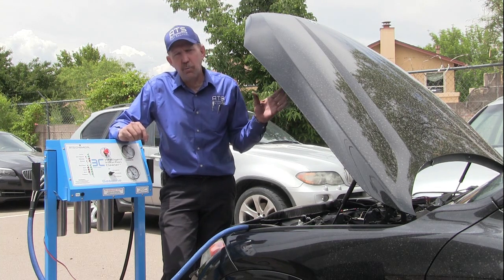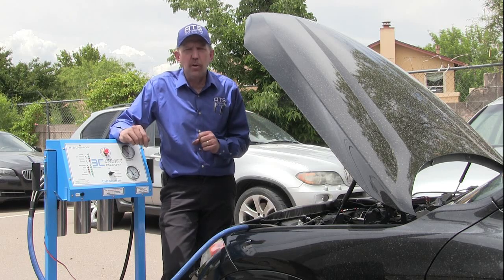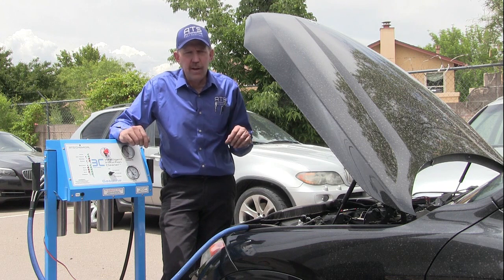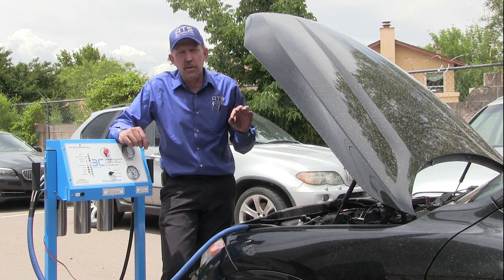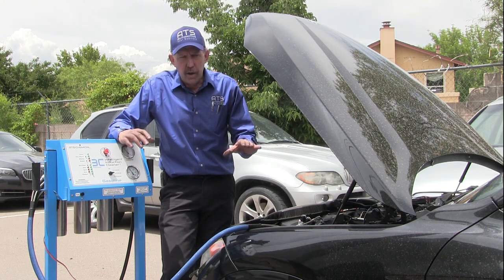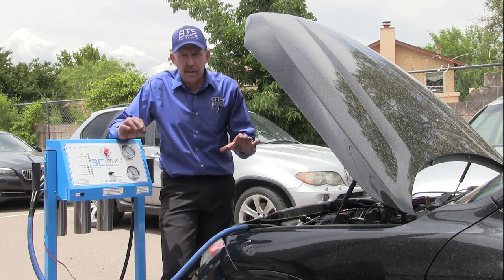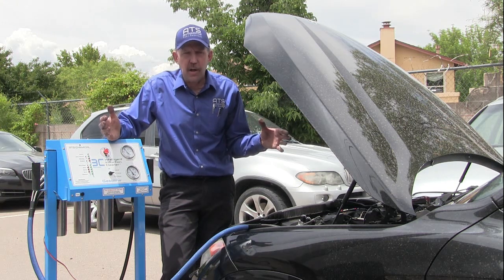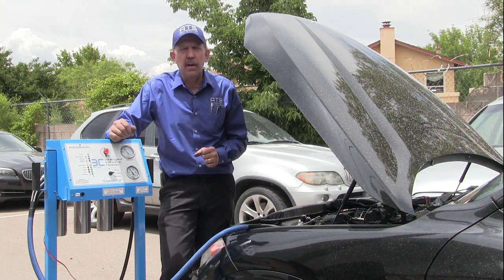Once you start the car and we're driving it, we need to be on a road where it's safe to go to a wide open throttle position. We're only in first gear, so we're not getting a top speed. What you're going to do is slowly roll into the throttle, and if there's no audible pre-ignition, just go ahead and go wide open and let some air flow, and that's clearing all the chemical out.